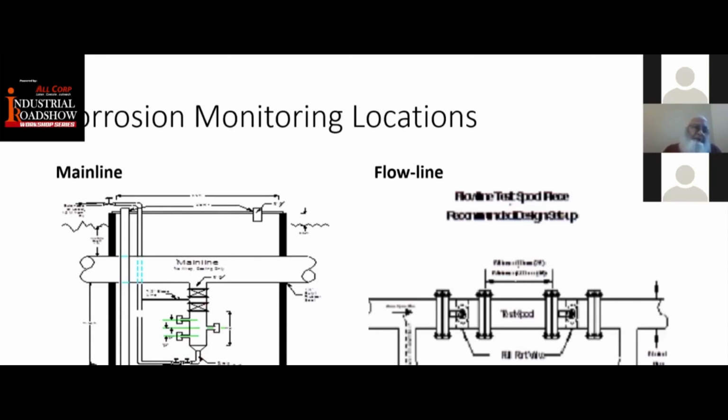And this boot has to be emptied from time to time, and at least when the people go for the corrosion monitoring, because mainly we install the ER probes there. So we have to eject the entire liquid from there, to make sure that the people who are working there are not subjected to any kind of hazardous situation. And at the same time, the people there monitor the actual corrosion readings.